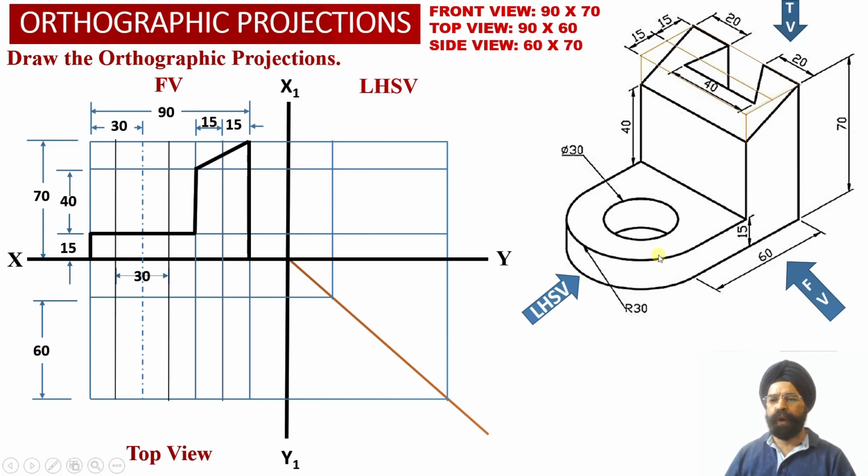Similarly, corresponding to this horizontal web, this portion starting from this point up to the center point will be observed once again as a true shape in the front view orientation, that is up to the center point starting from this position. So this portion is visible to the observer as a true shape, while this portion of the rectangular projection is the apparent shape projection corresponding to this horizontal web.